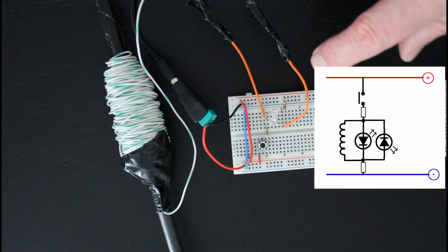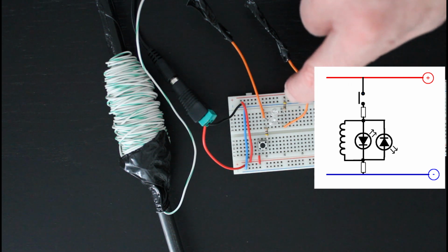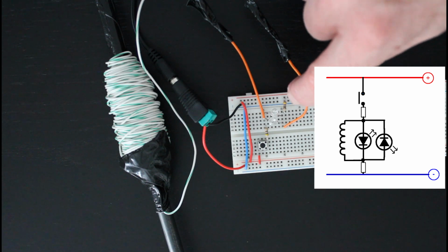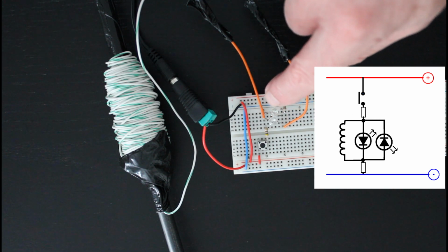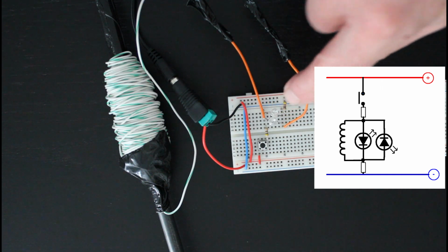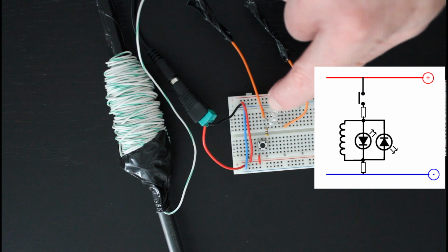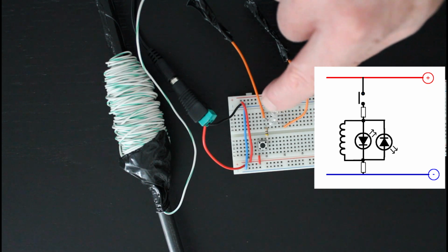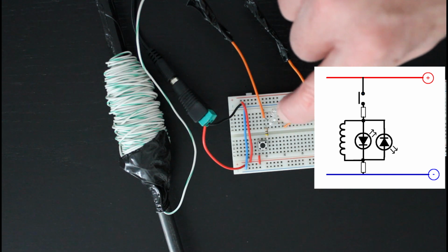So we now have a slightly modified circuit where the connection to the ground rail has been replaced with another 47 ohm resistor, and that is there to provide a little bit of protection for this second LED. Although you won't be able to tell just from looking at the breadboard, trust me when I say this second LED has been wired up so that its polarity is reversed compared to the first LED.